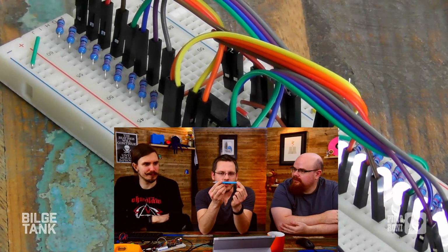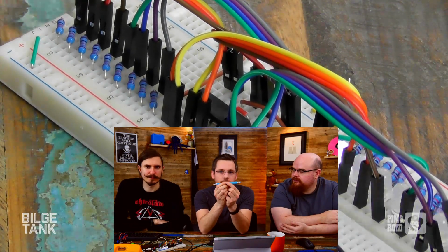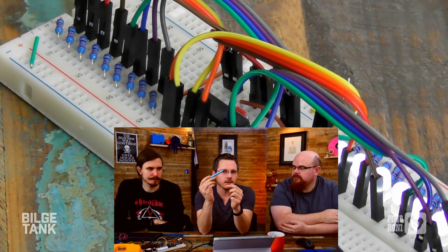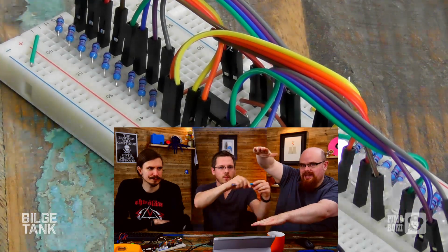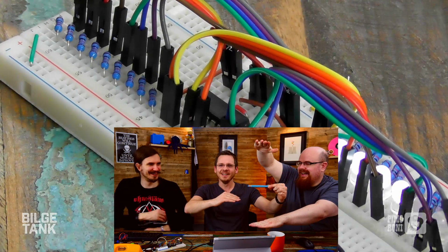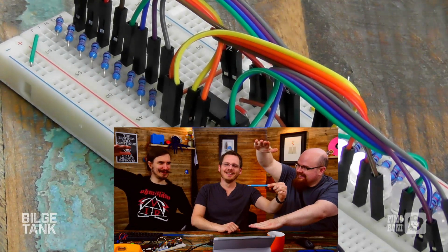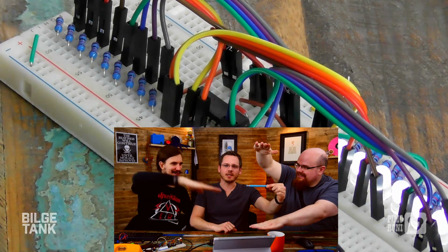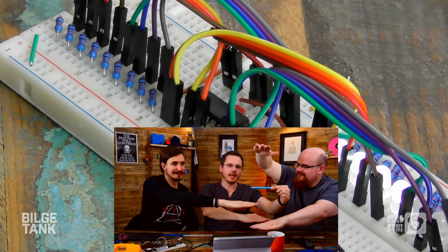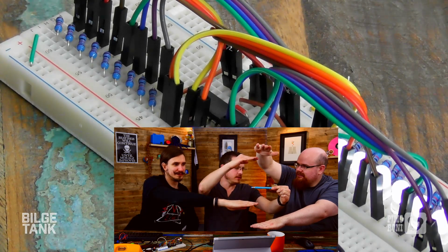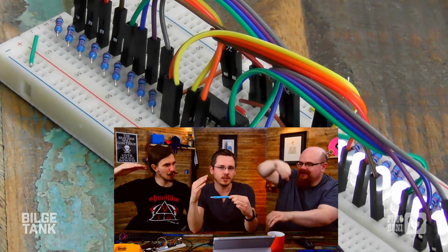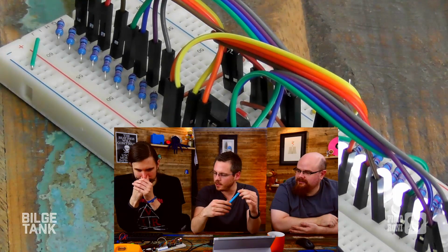So you can actually make an ADC with that, where you set your reference voltage at 2.5 volts, say on a 5-volt circuit, have a single comparator, and if the voltage is higher than 2.5 volts, you've got 0 and 5 volts here, and 2.5 volts right there, and the signal. So when the signal is compared, the output will slam down to 0 or up to VCC, essentially down to ground, up to VCC. And that means that you can tell whether the voltage is above or below the voltage you're currently sampling.